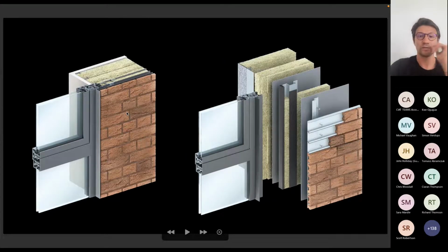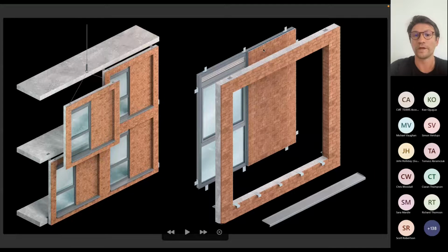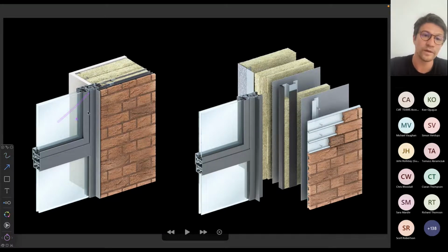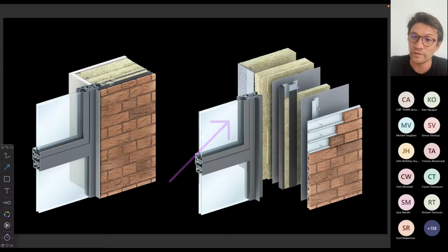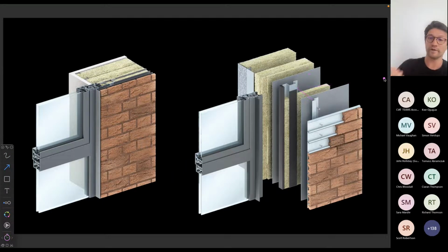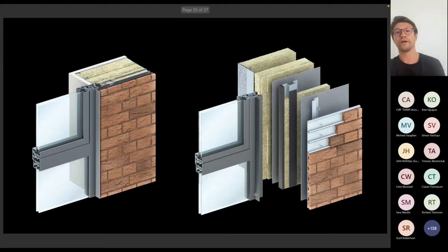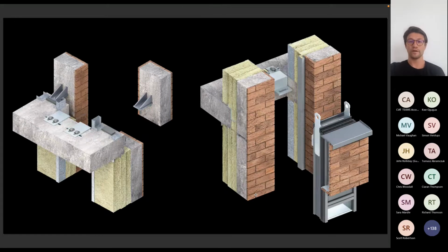And in order to achieve that, that window is installed with the brick slips fixed to it, as a brick slip assembly here. So you will have a window frame, but instead of the glass, you would glaze in a certain metal frame that would then receive brick slips, mechanically fixed, non-combustible, to be installed to the precast unit. Then that would be craned into position and installed as the precast unit. So we have a hybrid of precast and brick slip assembly in one location.